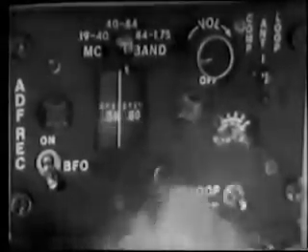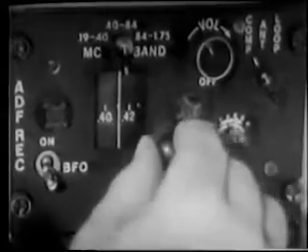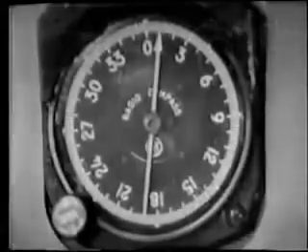Okay, now we'll tune the Cairns non-directional beacon and work our way back to Cairns Field for a practice approach. The student checks the chart for the proper frequency, sets the function switch to antenna position, selects the proper frequency band, and tunes to 410 kilocycles. He listens for identifiers. He switches to compass position and tunes for maximum deflection. He now checks the indicator, and we continue toward the station.